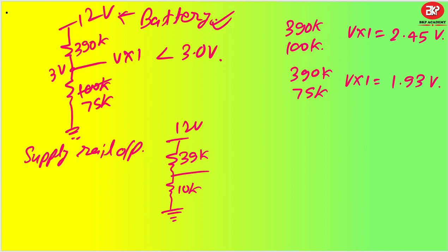We have a battery voltage input which is close to 12 volt. First of all, our aim is to understand what my V reference of ADC is. Let us say V reference of ADC is 3 volt. Our understanding is the analog input going to the ADC must not be more than 3 volt. It should be lesser than 3 volt, maybe 2.5 volt maximum, or 2.2 volt maximum, like that.